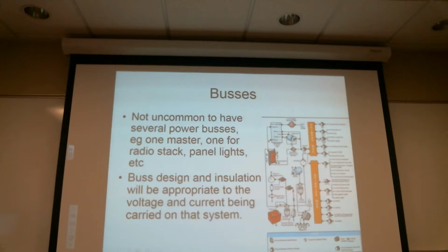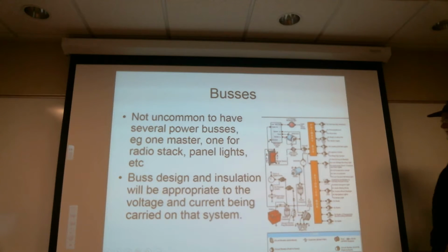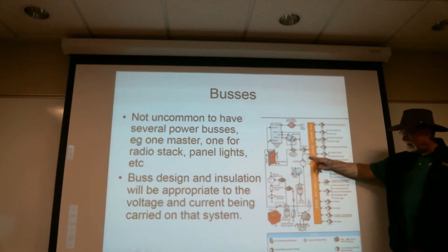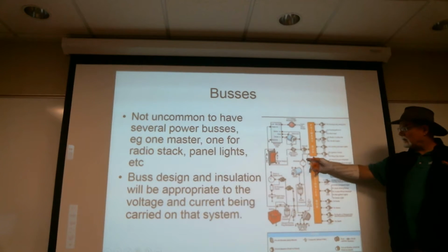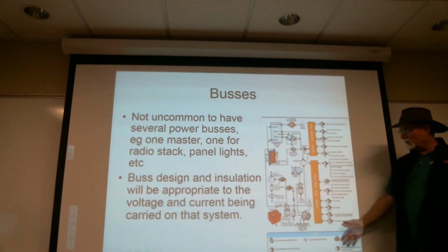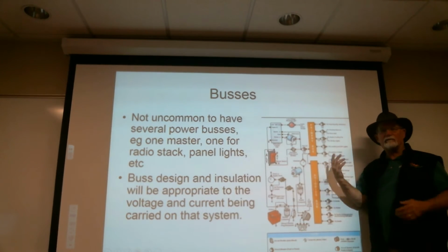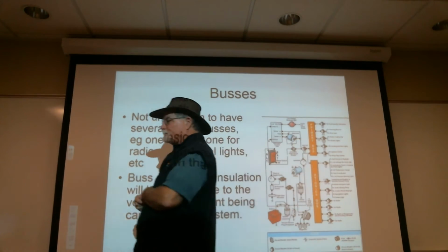They're then going to shut the avionics bus back off, fiddle around, getting the engine started, other checklists, do a whole bunch of other stuff. Then, once they're ready to go, they'll kick the avionics bus back on, call up ground, and get the clearance to start taxiing and do whatever they do. So the advantage of that is if I've got one switch in here that lets me actually shut that off, I can then shut off a bunch of devices during start phase or other operational phases.